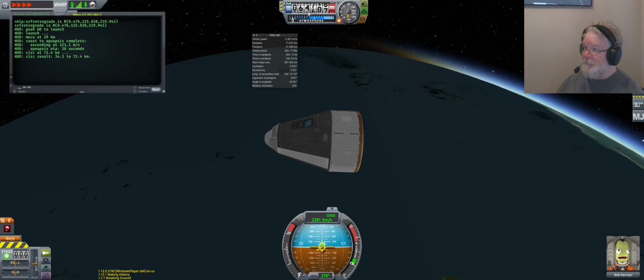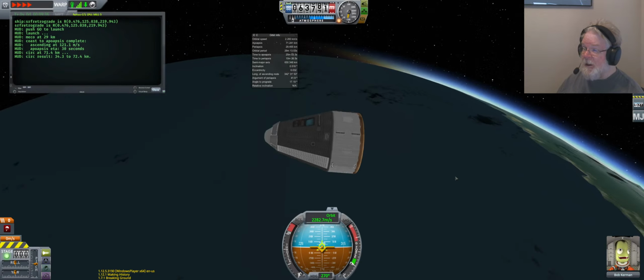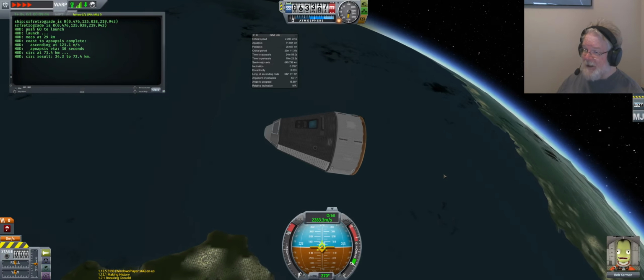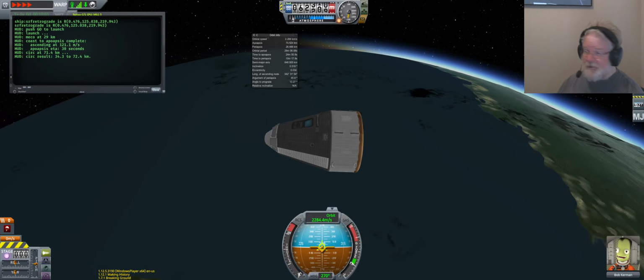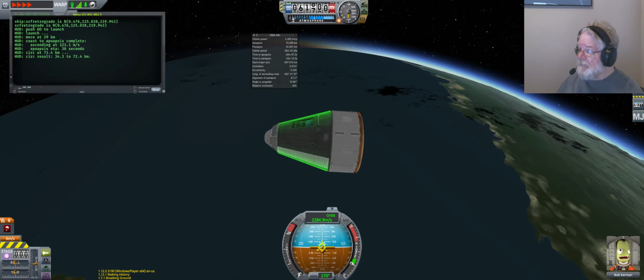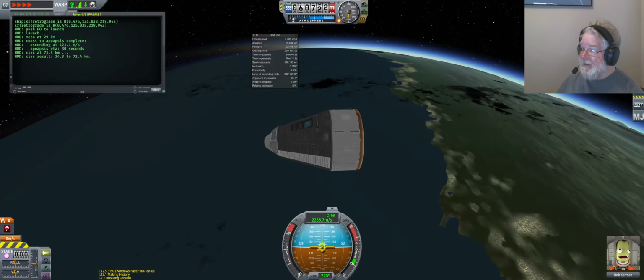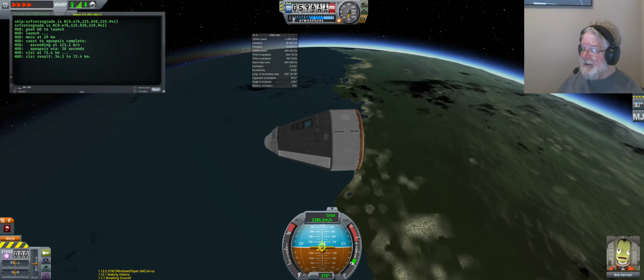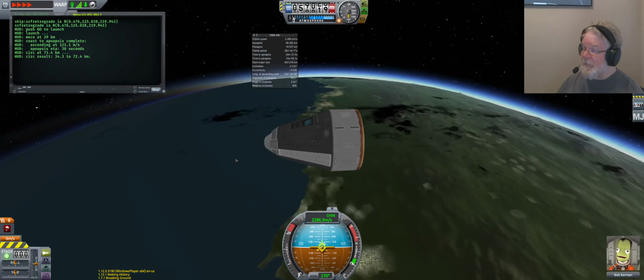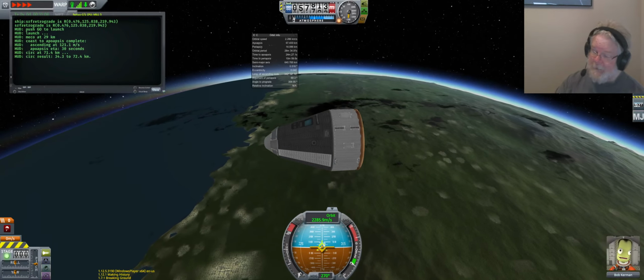And at 40,000 feet, it will go from steering retrograde to pointing up. Well before that, we should actually be, what was it, 40,000 feet I did that, or 10,000? Might have been 10,000. Looking at the script, it is 10,000 feet. So at 40,000 feet, we go from retrograde to surface retrograde, and at 10,000 we go to up. So we're still steering orbital retrograde now.